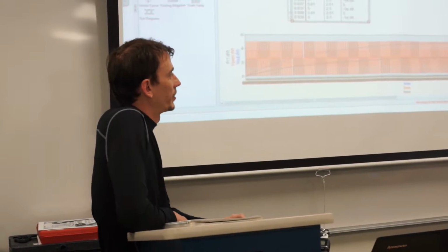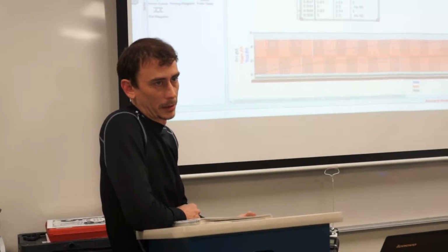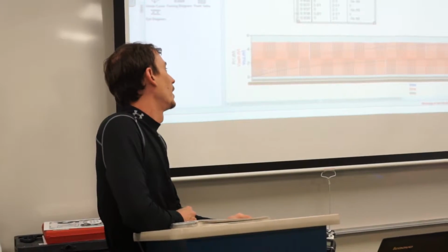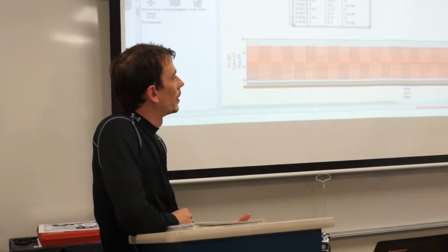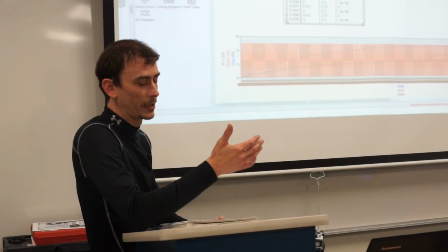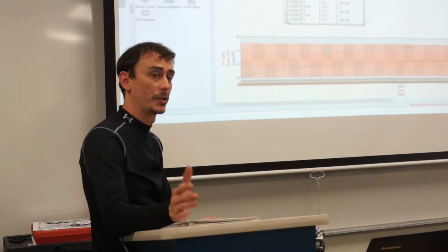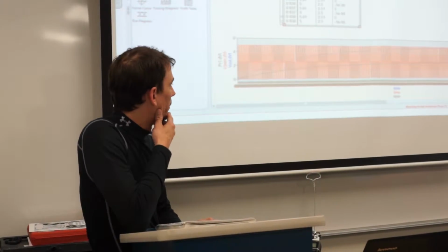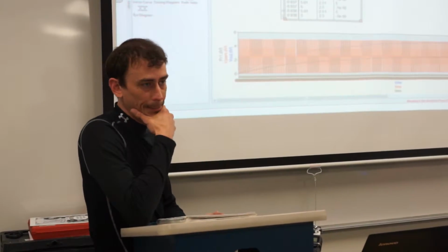Now through all of this, I still was having a problem getting that noise down within my 19 millivolt requirement. As it turns out, looking into other parts of the circuit, the easiest way, I felt, at least within the means of what we had covered in class, I had gotten it as close as I possibly could using the resistor and capacitor values. What else can we change in the circuit? I had to step back and increase the clock speed. I just started by doubling it.